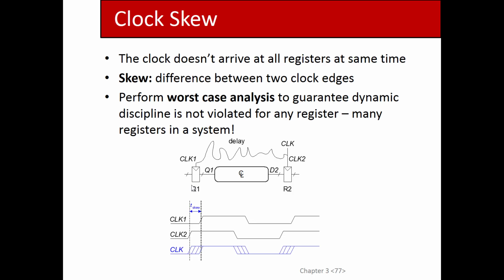The clock network is problematic because it's so big and connects to so many things that it's made of a lot of metal, meaning that it has a lot of capacitance, meaning that the clock network is going to be hard to maintain the clock speed you want because you've got to drive a lot of capacitance. But also there's this clock skew, because if you look at the clock at various points on the chip, they may not be synchronized. Your clock edges may not be synchronized at different points on the chip.